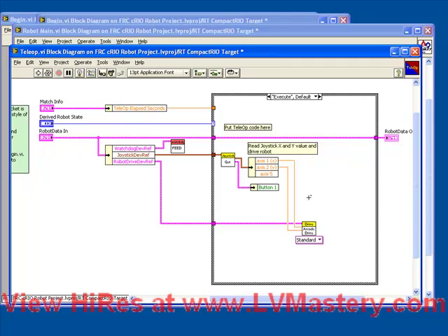Perhaps you have some sort of steering loop, which is parallel, traction control, propulsion, functional mechanism, any sort of other type of loop that you might have in parallel. You want to put all the commands together into one global variable. And it's important to remember that that global variable can only be written to by the Tele-Op.vi. However, it can be read by all of the different parallel loops. So let's create it now.